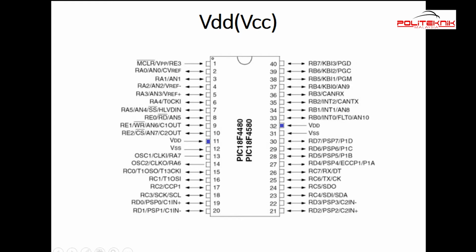2 pins are used to provide voltage supply to the chip. The typical voltage source is 5 volts. Some PIC18 family members have lower voltage for VDD pins in order to reduce the noise and power dissipation of the PIC system.